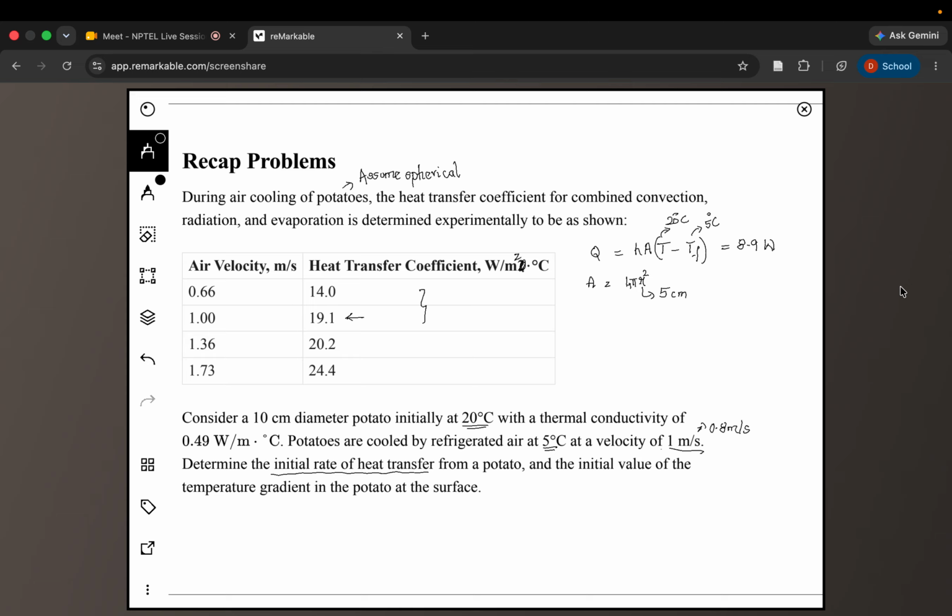Okay, sure. From what we understand, in this particular week we will be discussing scaling relations, where we will find that the Nusselt number is proportional to Re to the power m. It is always of the form of some power. All the heat transfer correlations that we will be encountering in this course keep coming up again and again, and they follow power laws. So the heat transfer coefficient will also follow something of the kind C1 times velocity to the power n. It would follow a power law.